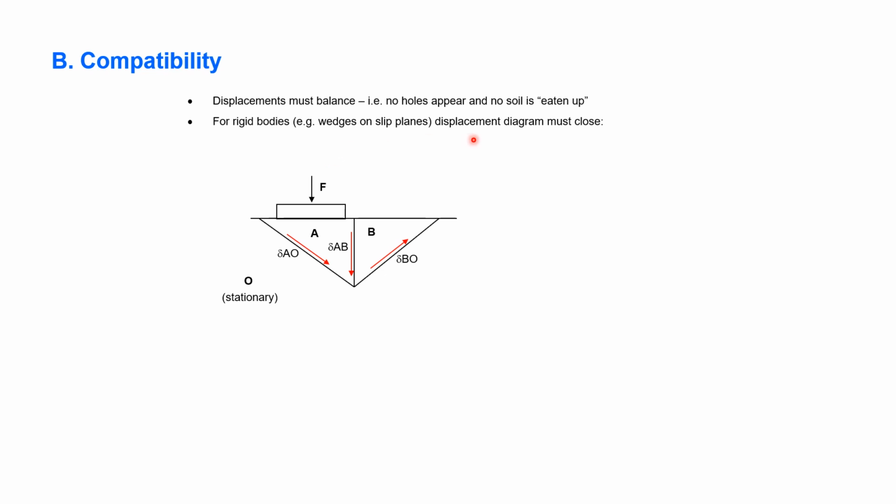Now we turn to compatibility. Compatibility means that displacements must balance, just like force is balanced when you were resolving forces a moment ago. It means that no holes must appear in the soil, and no soil must be eaten up or disappear.